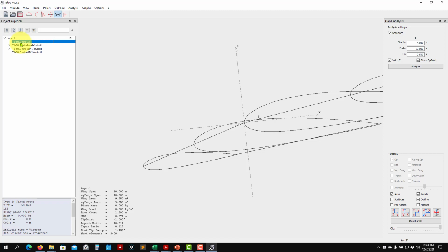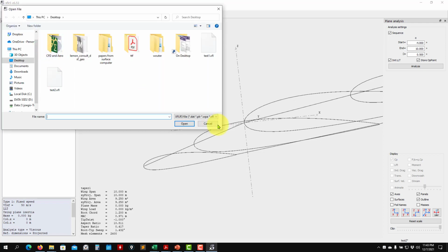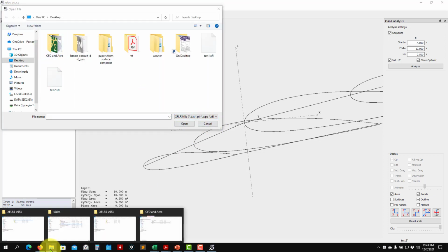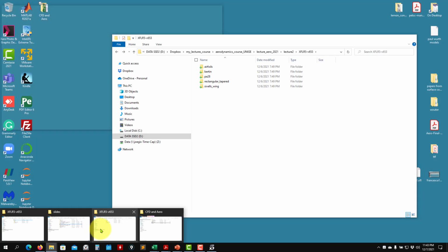The LLT, as formulated here in this software, is only for the main wing, but you can correct it. Now, if you have a tail, you just need to add that downwash. Also, let me show you another case in the files that you have, for instance, you can add winglets. Remember, LLT is just the planar wing. For the winglet you use the BLN or the panel method.